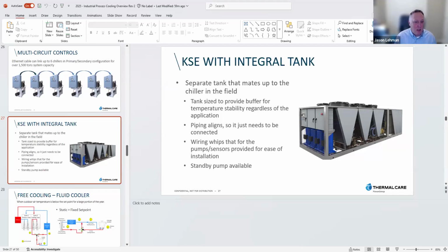And there's a standby pump with automatic switchover as well. Everything's designed so that if something happens, at least initially, you're able to run at least partial load. That's one of the things with industrial cooling. It needs to run, and it needs to run reliably. If it doesn't, it needs to be able to at least run long enough so people don't lose all of their production.